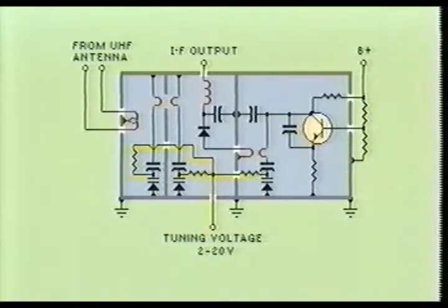Notice the electrical line connecting the cathodes of each varactor diode. This line is used to simultaneously adjust the capacitance in each stage. Since a specific voltage represents the same capacitance to each of the varactor diodes, all three varactors are a matched set.